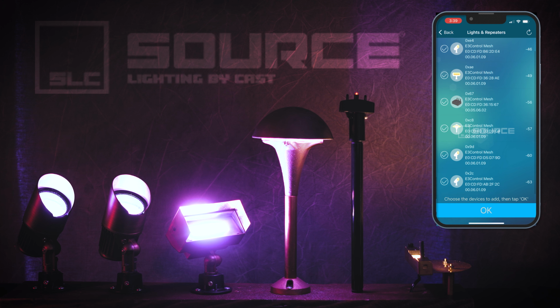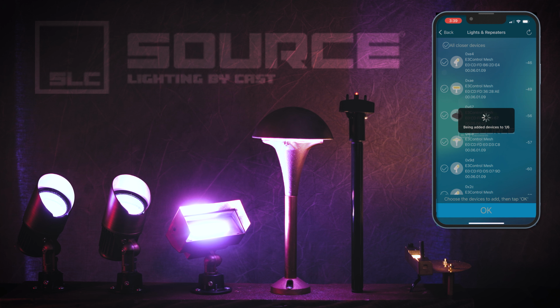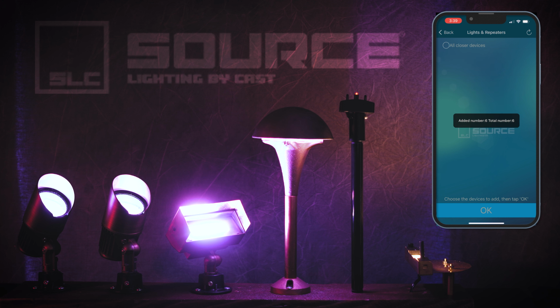Check all the boxes for the fixtures you want installed on the app, then click OK. You will now see the lights being added to the configuration. If you get a message that warns about a weak signal, there may be impeding factors weakening the signal. To resolve this issue, you may need to add repeaters to your lighting system or stand in a different position on the property closer to the weak signal fixtures.